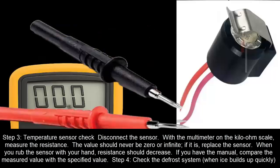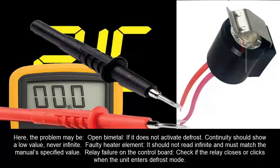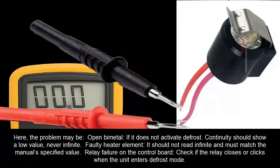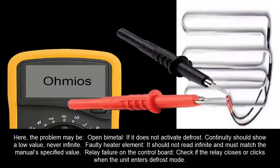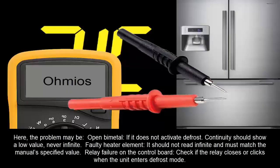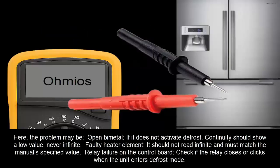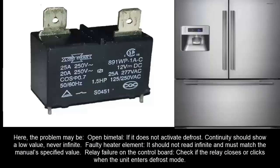Step 4. Check the defrost system when ice builds up quickly. Here, the problem may be an open bimetal if it does not activate defrost. Continuity should show a low value, never infinite. Faulty heater element. It should not read infinite and must match the manual specified value. Relay failure on the control board. Check if the relay clicks or closes when the unit enters defrost mode.